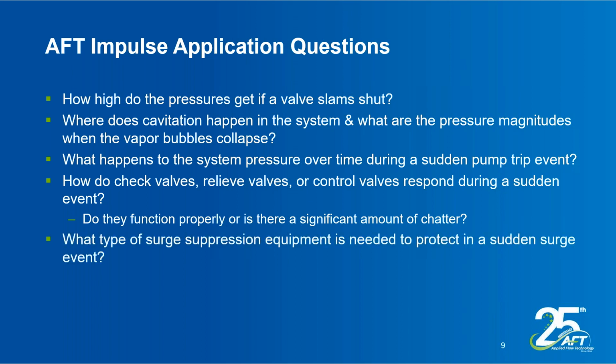What type of surge suppression equipment do you need? Do you need gas accumulators, relief valves, surge tanks? Different methods are available to help you protect your system to ensure that you don't have pipes bursting or collapsing.